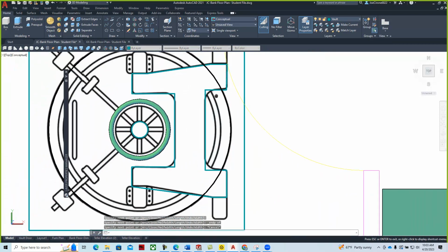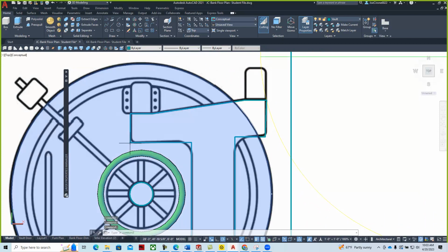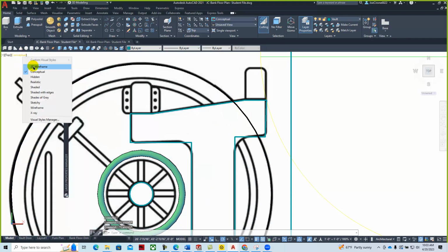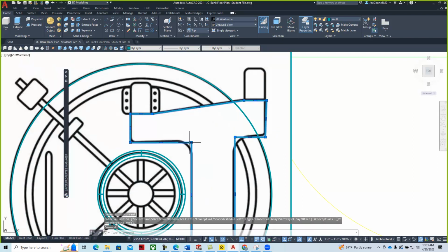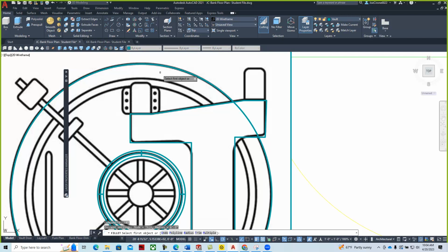And so I have a basic shape here, and I can soften up the corners a little bit if I get an idea of my lengths of my geometry. Let's get out of conceptual. That tends to glitch it. And if I look at the length, it's about 10. So we could put a nice 2-inch radius on these fillets. And so we'll say fillet radius, we'll say 2. I'll put a fillet right here.